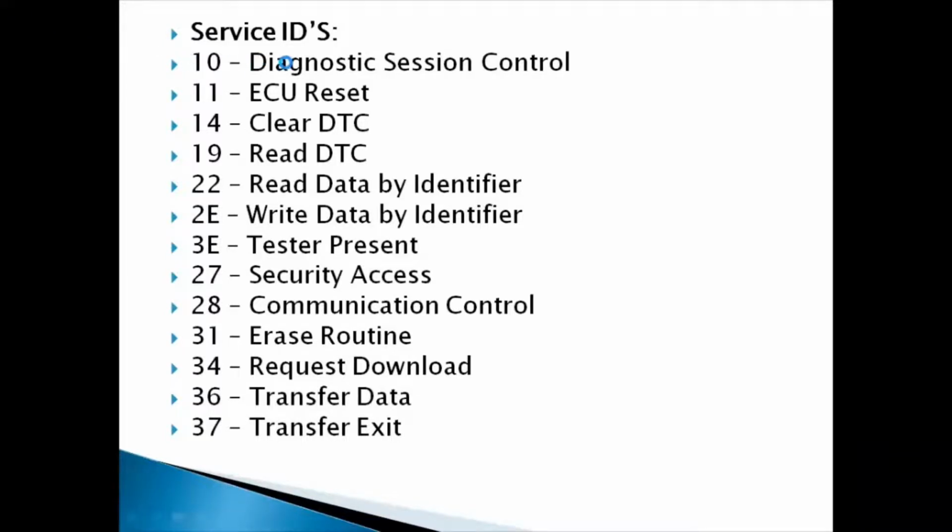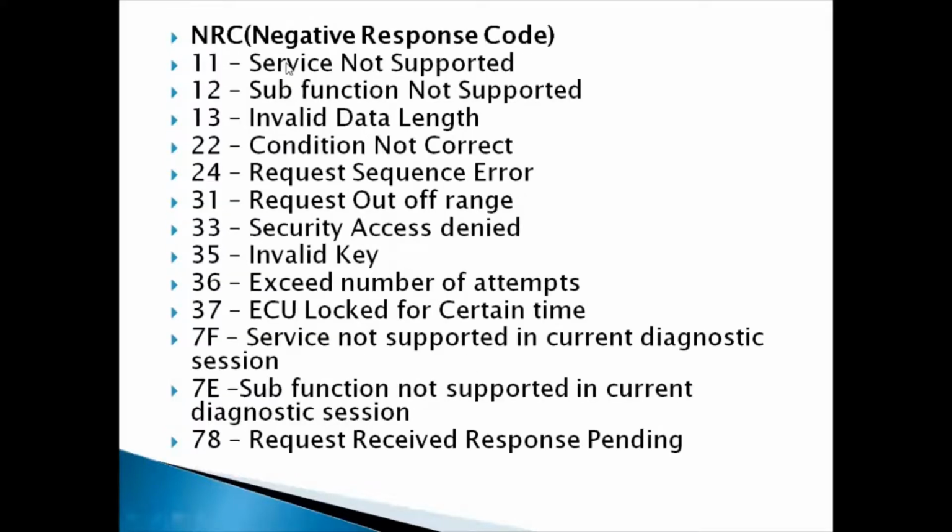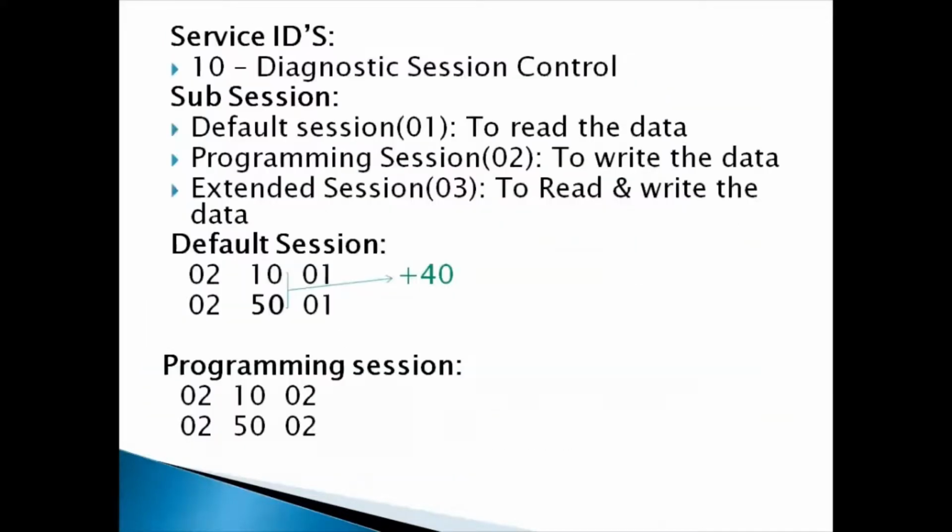For now we have 10, right? 10 is nothing but diagnostic session control. In this 10 diagnostic session control, again we have 3 subsessions. One is the default session, and the others are the programming session and the extended session. The default session sub ID is 01. In 10, 01 is the subfunction, and 10 is the service ID. This subsession 01 is the default session.